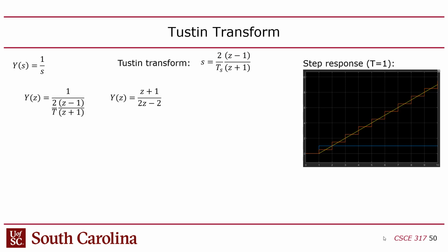It's changing in a way where the way the Tustin transform works is it guarantees that the continuous version crosses the midpoint between each two sample points, right? So this orange line is the discrete version of the transfer function you get with the yellow line. You guys with me?